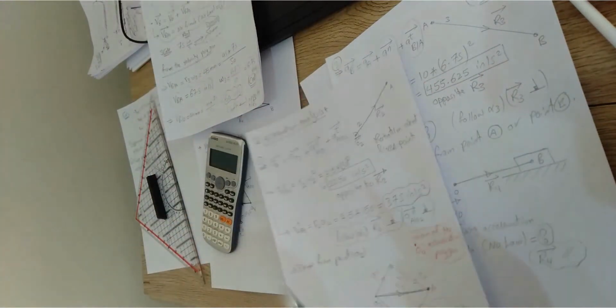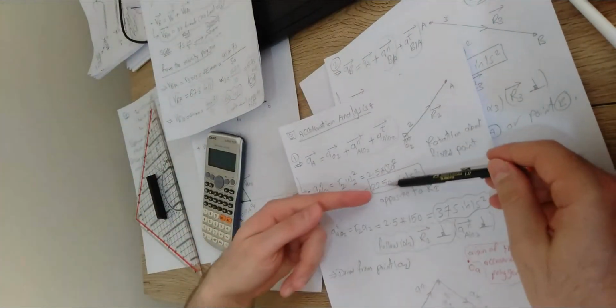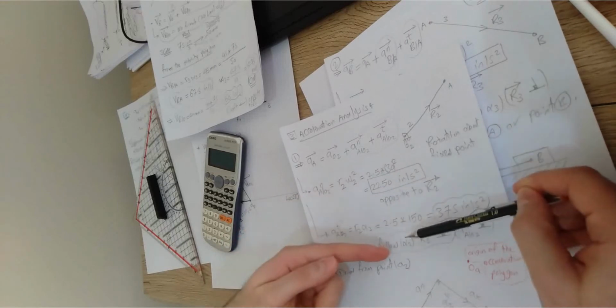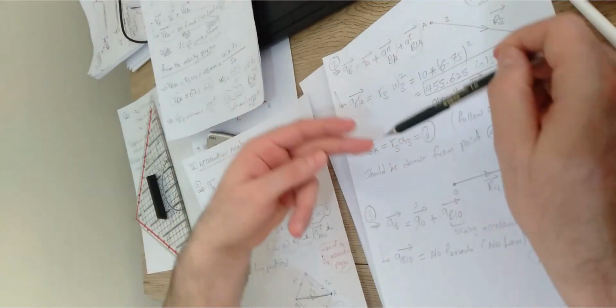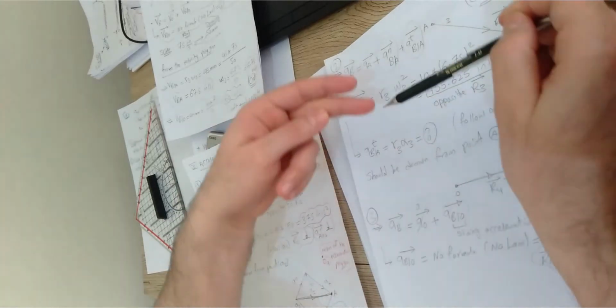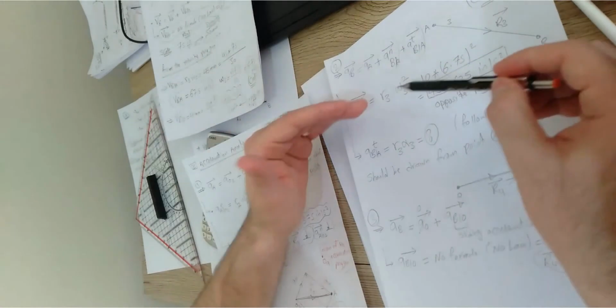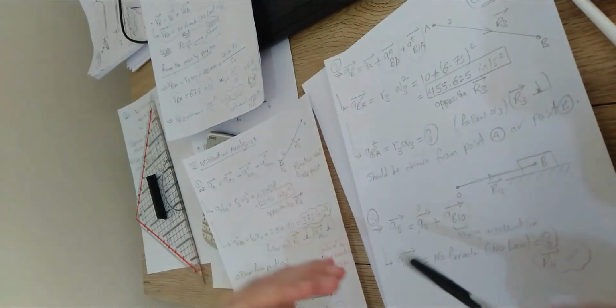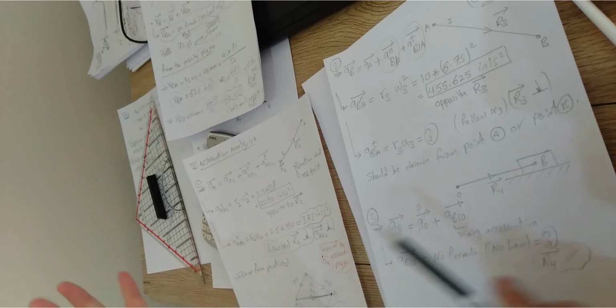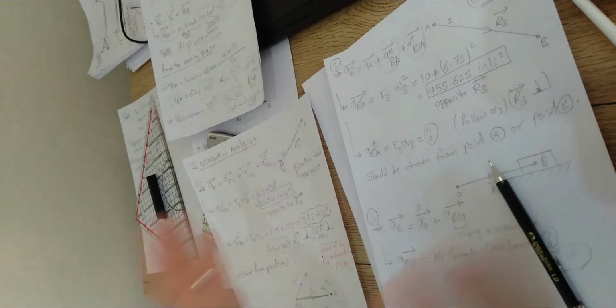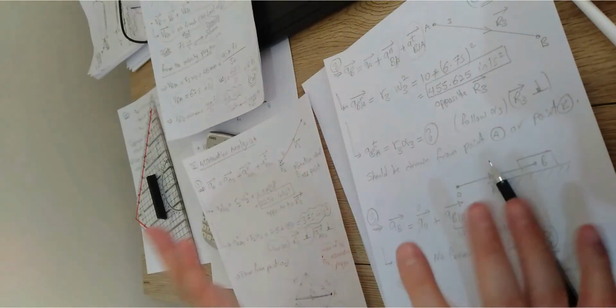But for each one of these drawings, like this one, we're going to draw 2 lines, not just 1 line, because we have normal and tangential. Here we're going to draw 2 other lines. We have normal and tangential, and the normal has a value, the tangential we have no clue, right? In addition, we have only 1 line for the slider that should be represented in the acceleration polygon. So the acceleration polygon should include 5 lines in total. Make sense?